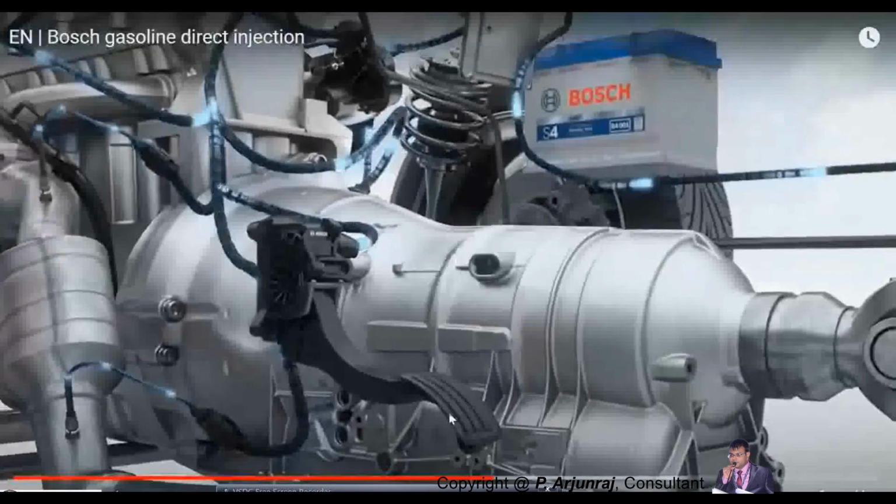I told you, based on the accelerator pedal, so based on the speed, when you increase the accelerator pedal, the speed gets increased. Accordingly, the fuel injection pressure is also going to increase, and the quantity of fuel injected into the system also varies. Again you have the sensor. I told you about the different types of sensors when I was explaining. Based on the accelerator pedal movement, the accelerator pedal sensor gives the sensing to the electronic control unit. Accordingly, the fuel injection quantity and the pressure is maintained in the system.